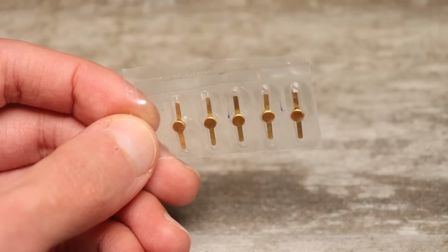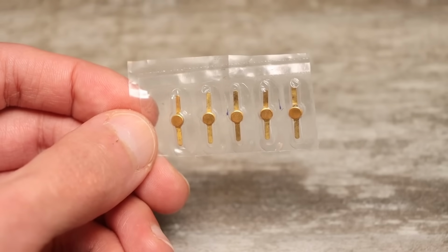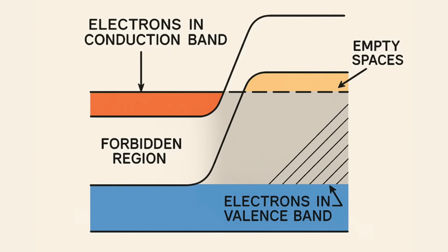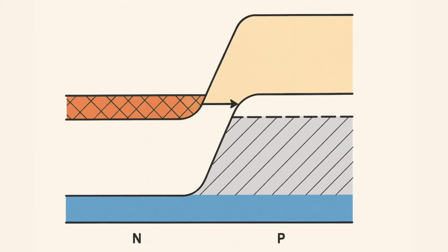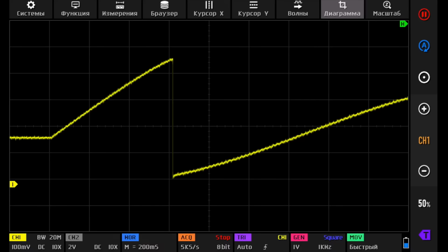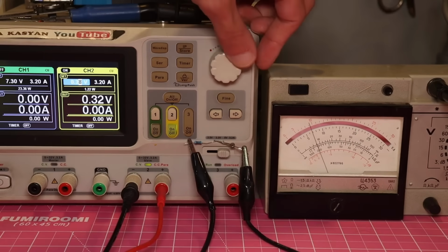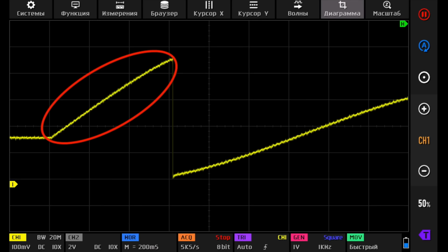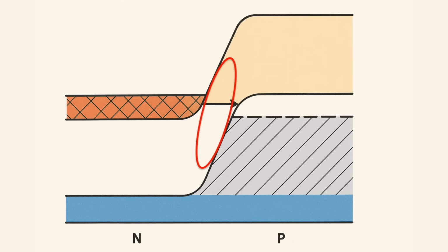The final formulation describing how a tunnel diode works could look like this. At a low forward voltage across the diode, electrons tunnel directly through the narrow barrier. The current starts to increase. In other words, tunneling happens specifically at this stage, at low voltages. You could say this current is the tunneling current. It's also important to emphasize that the barrier is extremely narrow, which increases the probability of tunneling. The narrower the barrier, the higher the probability.